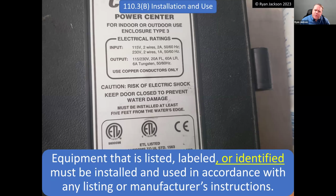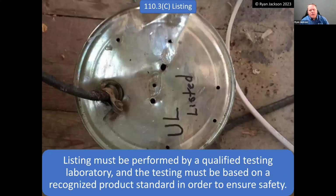So if you think about it with that in mind, now the code for the first time is really saying that you always need to follow instructions. So perhaps that's something that should have been in the code forever, but now it is. So we need to make sure we're following manufacturers' and listing instructions. The listing itself needs to be performed by a qualified testing laboratory, and the testing must be done on a recognized product standard in order to ensure safety.